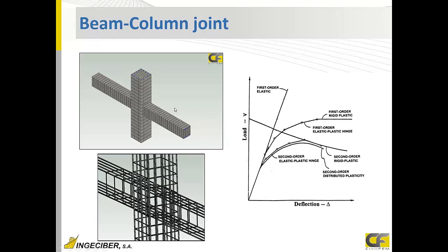Another way to perform nonlinear analysis of this building is modeling this bending moment curvature behavior of beams here with nonlinear springs on these connections. With those behaviors, if we are solving with first order results, we will have this polyline. At every one of these points, the bending moment goes over the limit of this union, and we will have a pin connection.